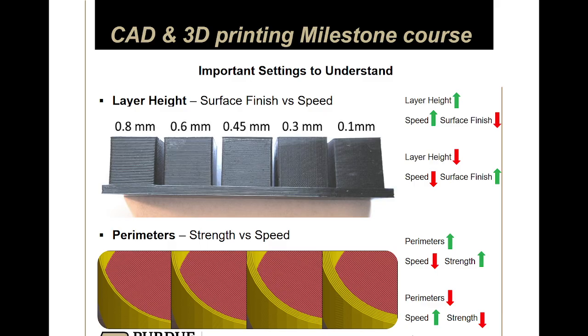3D printed parts, at least in FDM cases, are the weakest on the layer lines. So they typically like to shear on the layers because they don't always bond perfectly. So having fewer layers reduces the chances of failure. If you're looking to make really strong mechanical parts, sometimes upping that layer height can give you some benefits. But obviously, if you're printing things that you want to look really nice, decreasing that layer height will help you with that resolution.